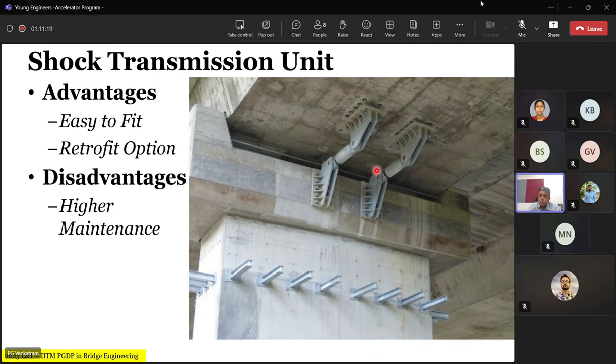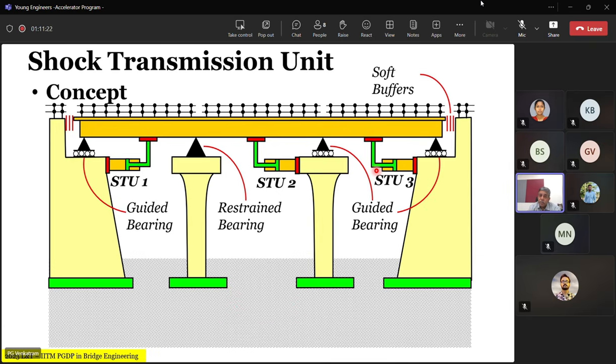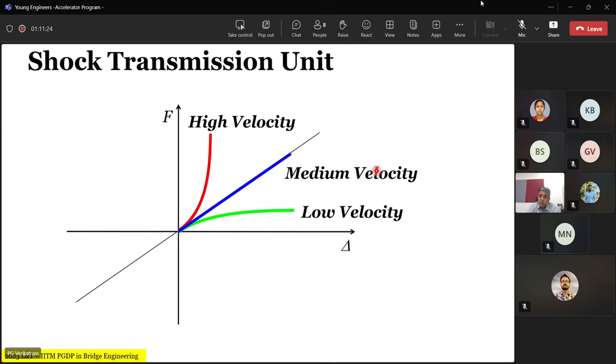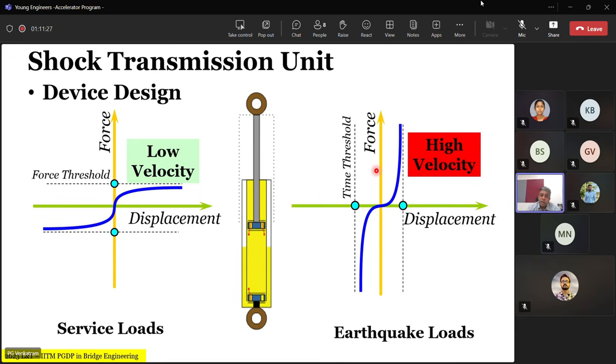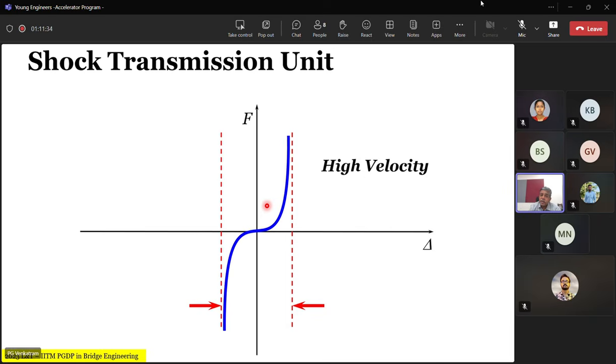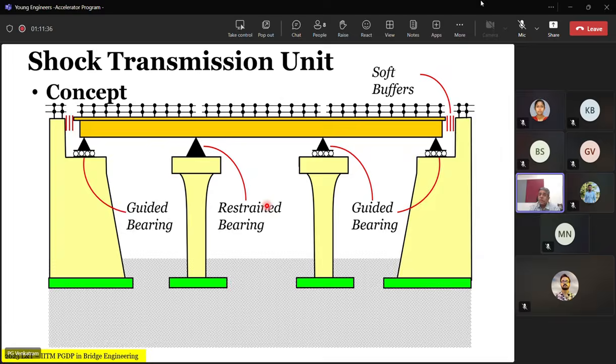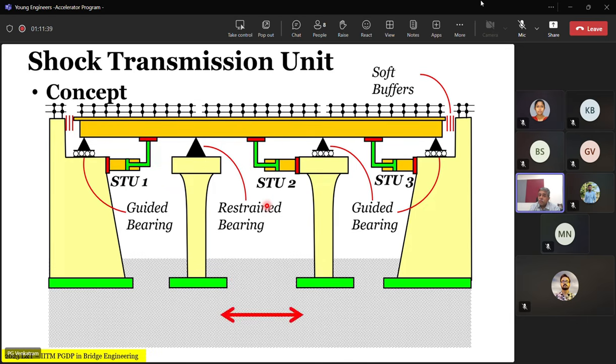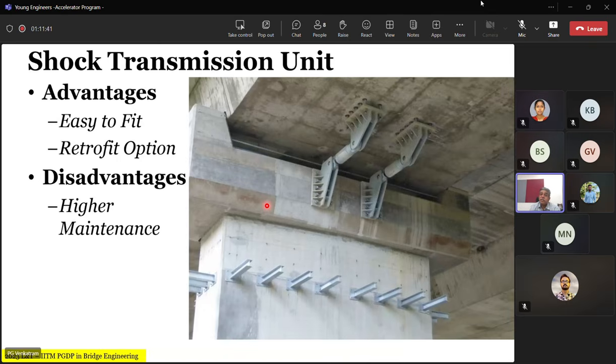See, remember, as I showed you the picture in the operation, I showed you that there is a viscous fluid inside. This fluid needs to be periodically inspected and verified that it is there. Since it's all a man-made creation, obviously there's a chance that it will leak, it will dry, it will change its viscosity, it can have so many things possible. Therefore it requires to be periodically removed, inspected, maintained, and reinstalled.